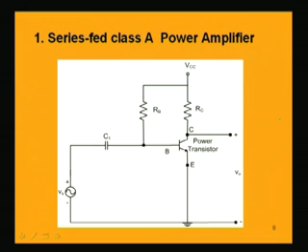It is using a VCC, that is a DC voltage, and the power being drawn is the DC power which is supplied through this VCC, and the power which is drawn is VCC into IC, where VCC is the DC supply and IC is the DC collector current.